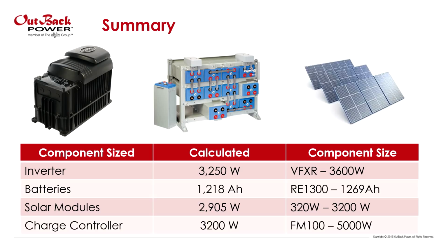All right, so now we have calculated and sized all of the components, and it all stemmed from knowing the loads, both maximum power and daily energy, not square footage. We have sized the inverter for power. We needed at least 3,250 watts. We calculated that. Remember, having that energy bill, if it's an existing site, is way more valuable than calculating it. So the VFXR can provide 3,600 watts, so we're going to move forward with that inverter.